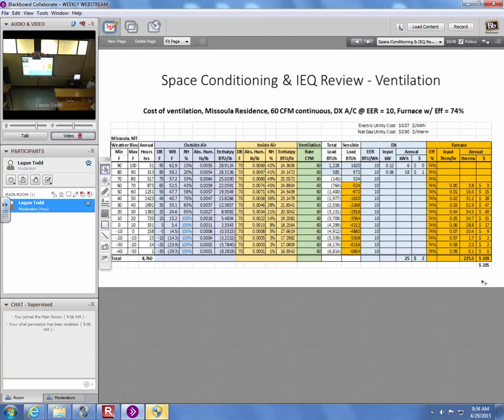Okay, so if you think about it, depending on your house size and efficiencies and everything, a lot of us might spend somewhere close to, let's say, $100 a month on heating during the winter months. So let's say in a year you spend $600 on your furnace bill. This says that the ventilation might be a third of that. So maybe a third of your heating bill is just for the air that comes in as ventilation, driven by an exhaust fan or whatever system you have to bring that in. And then there's an infiltration load that I'm not showing here as well.